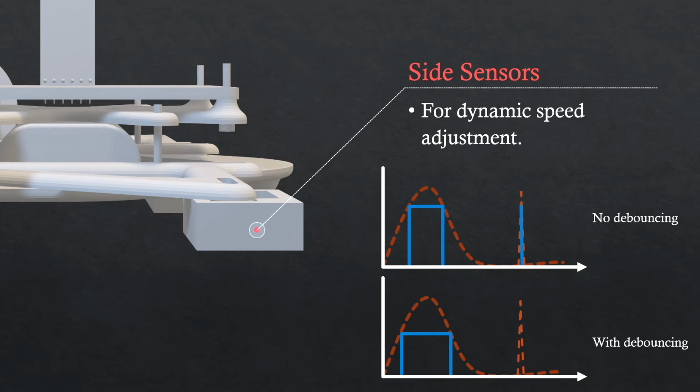To detect corners and straights, some modular code was implemented that detected if it was in a corner or on a straight depending on if it had odd or even in its banks, toggling the LED appropriately to be turned on the straights. There was much inconsistency with the sensor detection, so debouncing and a sensor light shield was implemented to counter this.